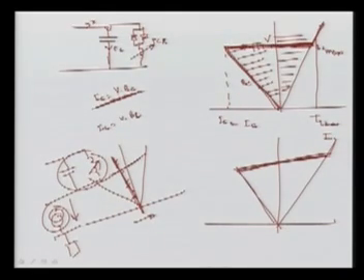But sometimes we have to go for another characteristic, where we intentionally provide more slope for the loading of the line. With the regulation slope, the terminal voltage is allowed to be less in the capacitive zone and more in the inductive zone. As I said, here we require the voltage less and more here, because when we require the voltage to be more, then we have to go for this. The perfect regulation may result in oscillation, as I said. With perfect regulation, it will be oscillating due to the poorly defined operating point, that is, zero regulation. So here the operating point is not defined.